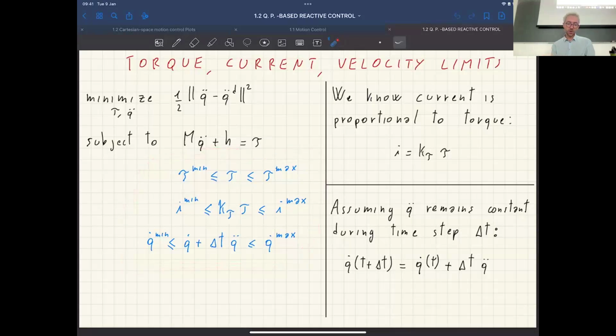For instance, we could add inequality constraints inside the optimization problem that say that my joint torques have to be bounded between certain values, which is a physical constraint. The motors of your robots don't have infinite torque. And so it's really useful if your controller is aware of those limitations and can take them into account when deciding what torques you want to apply.